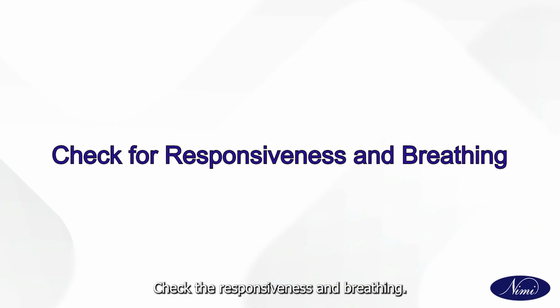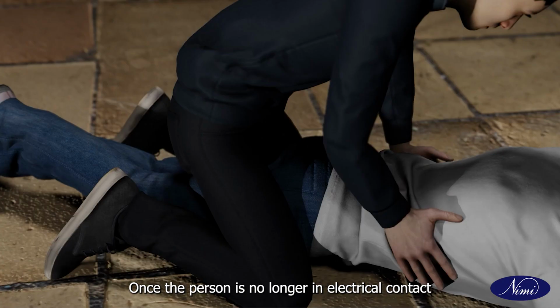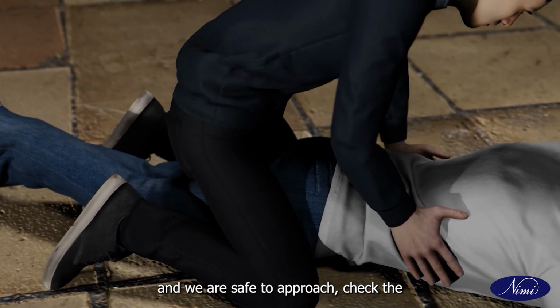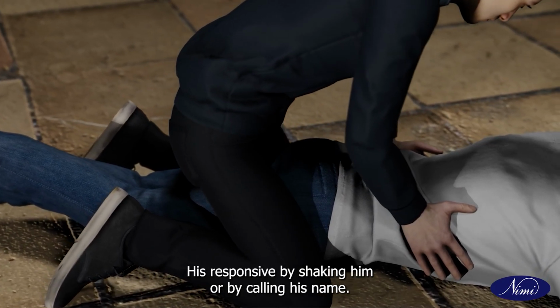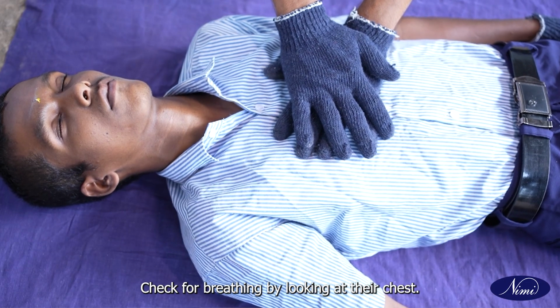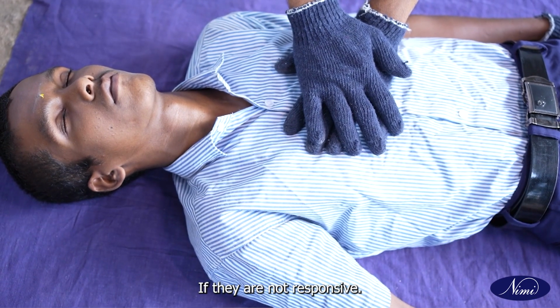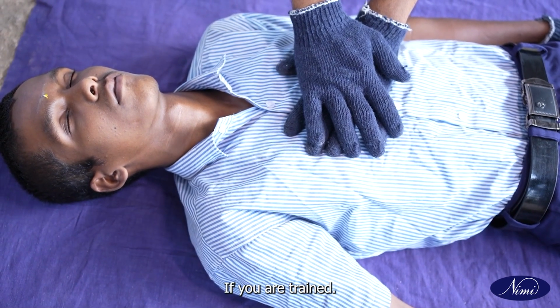Check the responsiveness and breathing. Once the person is no longer in electrical contact and we are safe to approach, check if he is responsive by shaking him or by calling his name. Check for breathing by looking at their chest. If they are not responsive, begin CPR if you are trained.